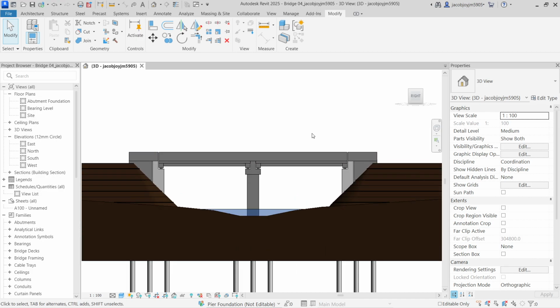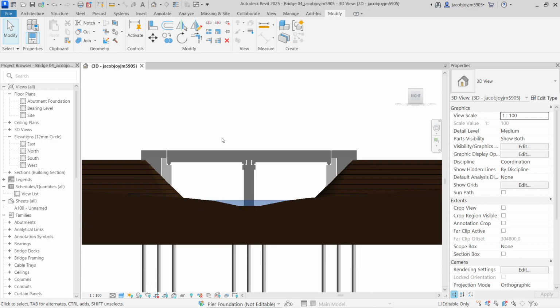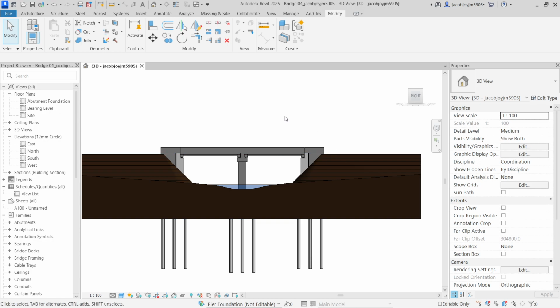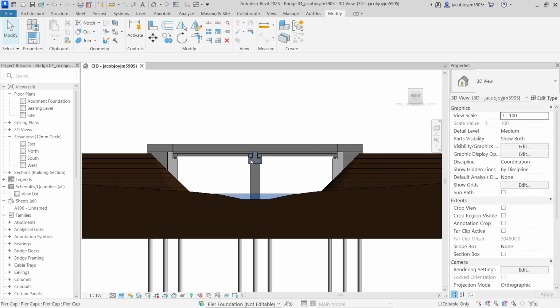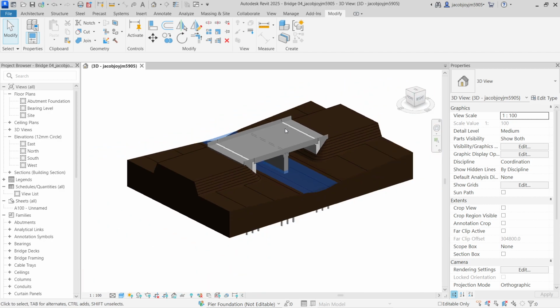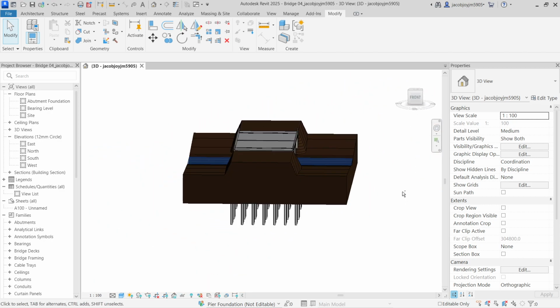Okay, in case you have to maintain a different level at the start and end, then you have to follow a reference plane. You can draw an inclined reference plane, and you can set that reference plane as work plane, and you can place all the items. So that will follow the work plane. Okay, so that's all about a quick read.